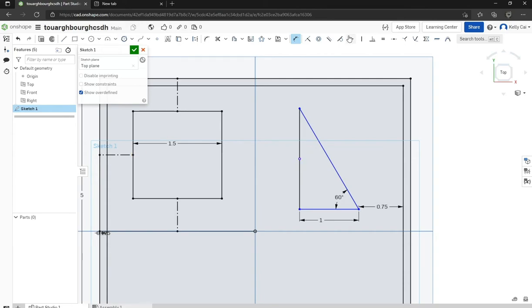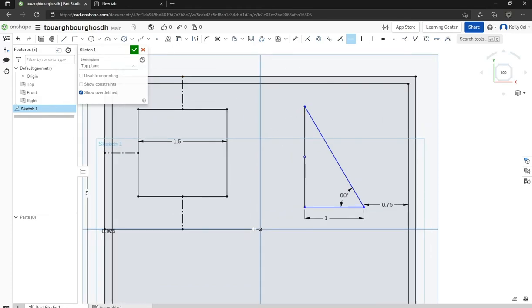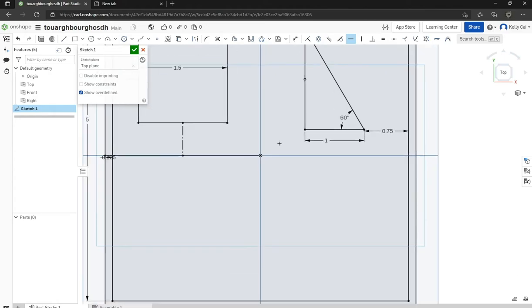Well, I can just use the horizontal, which means they'll have the same x value. So if you drew a straight line, both these points would be on a straight line. That's the same idea with the vertical. If you click vertical, then these two are technically vertical. If you drew a line through it, then both these points would be on it. So horizontal, boom. See? Now all this is as I mentioned.